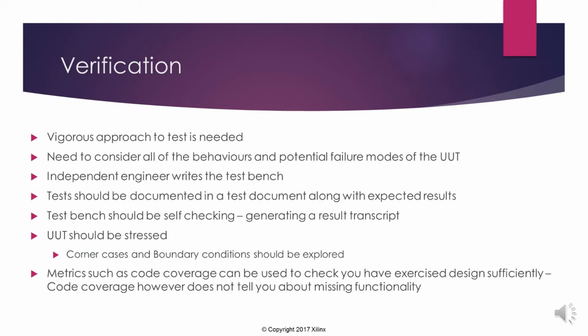So obviously we've gone through our design. We have our state machines, we have our counters, we have our signals, we have our data flow, we have everything that we want in there. Now we need to consider the verification, and we've got to be very rigorous when it comes to verification, because we need to test all the behaviours and the potential failure modes of the UUT, we've stressed them, and we've made sure that it behaves exactly as expected.